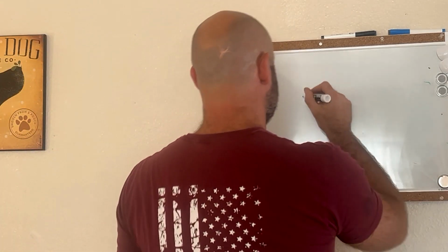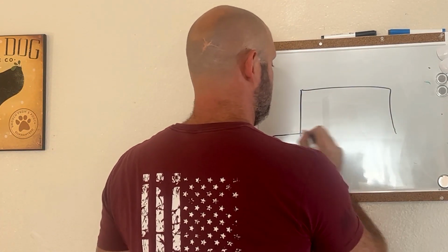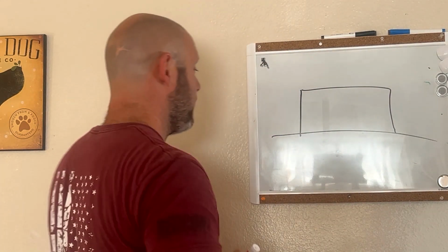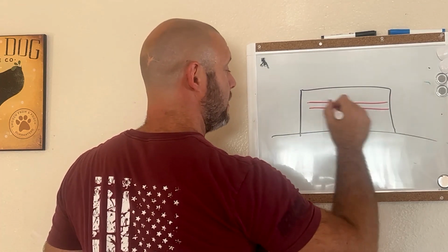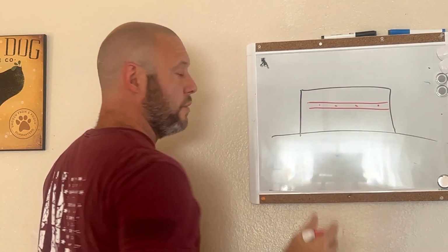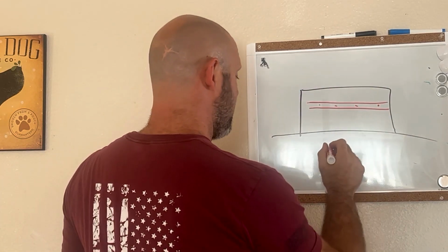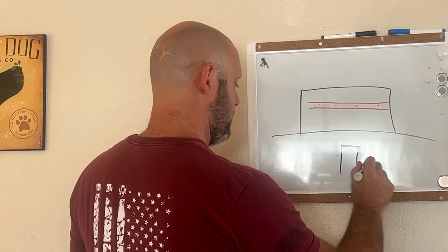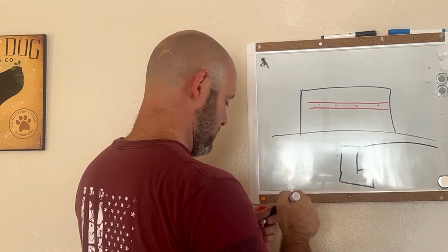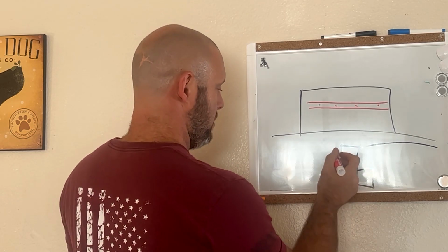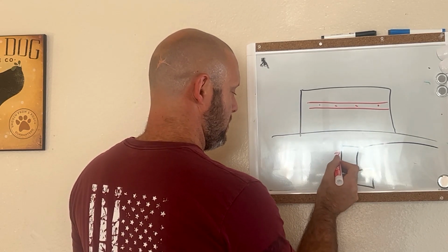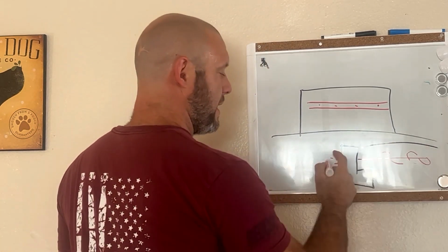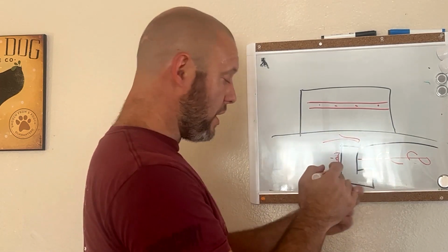So looking at the face of a retaining wall, that's grade right here. You can pop that I-beam on there, right? With soil nails or tieback anchors in there, and from the side view, that looks like little threads, boom, anchors here, right? In order to tie that and pull and straighten this guy up. That's one very common repair.